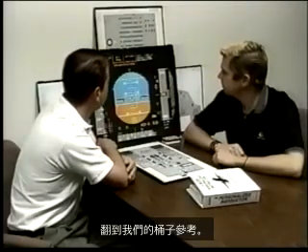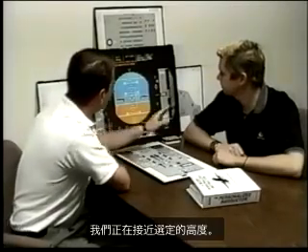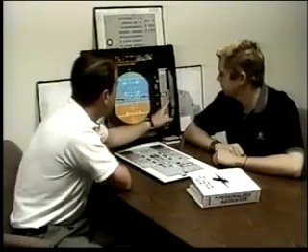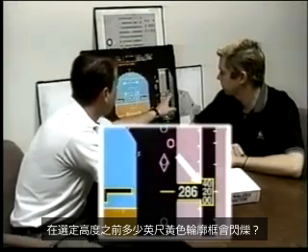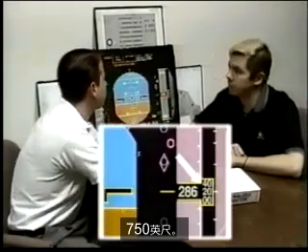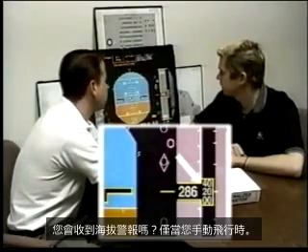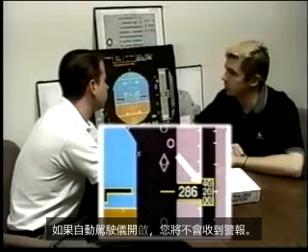Let's move over to our barrel reference. We're approaching a selected altitude. How many feet prior to the selected altitude will the yellow outline box flash? 750 feet. Will you get an altitude alerting? Only if you're hand flying. If the autopilot's on, you don't get an alert.